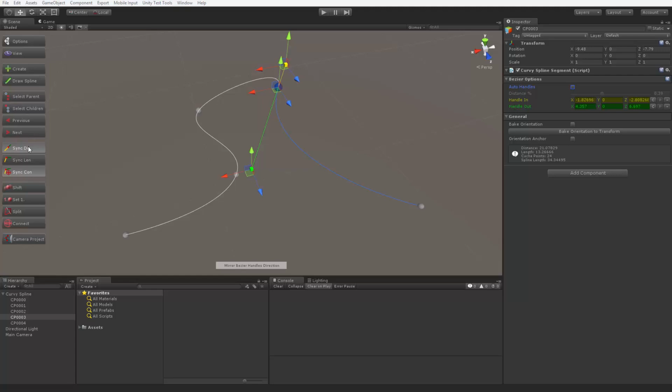It tells Curvy to automatically shift the position of an opposite handle as you modify one of them, keeping them parallel and therefore keeping the curve continuous. If you want to break the curve, for example to create a trajectory of a ball jumping on the floor, you can disable that option and position both handles independently. Or you can simply turn one of the segment ends linear by setting the handle position to 0.